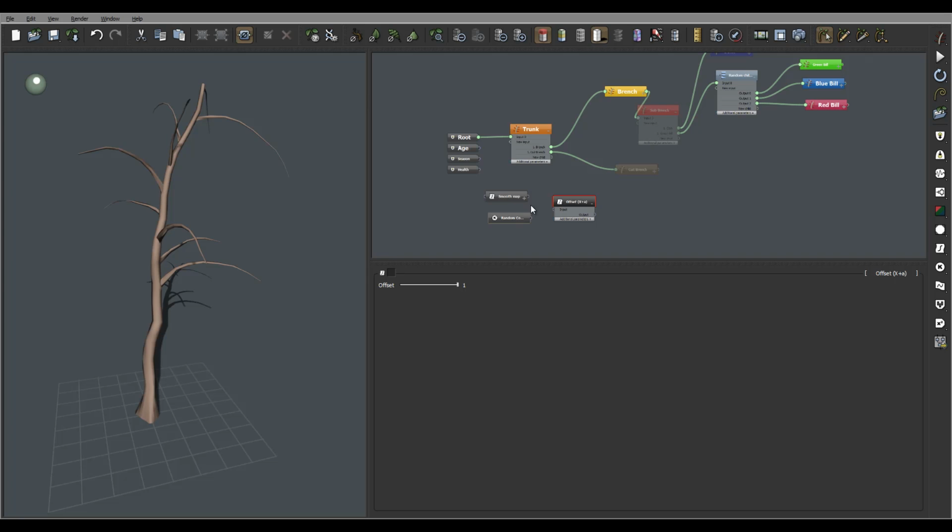So we'll take our smooth map one, and we'll connect it to the offset. We'll take 1. And in order to connect parameters, you need to hover over the name, and it pops up like an underline. So what we need to do is click connect parameter. Okay. Next, we'll take the connection from here and go to our random number.